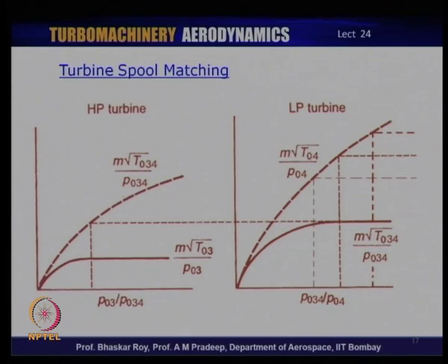of the HP turbine, and then from there you can proceed onto the LP turbine, and this is your LP turbine characteristic on the basis of its entry conditions, and you get this characteristic point on the LP turbine, which now as you can see is a good operating point, because this flat zone over here and indeed this flat zone over there, as you have discussed in the earlier lectures, actually correspond to choked flow condition, that is a steady turbine operating condition.